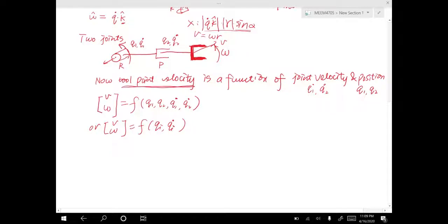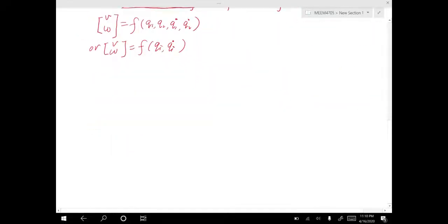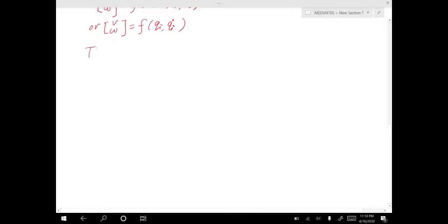If you are controlling a robotic arm and it has multiple motors to control each joint, and you want to finally control the end effector's tooling position and velocity, and now we're talking about velocity, so we want to control the end effector's linear velocity and angular velocity. Of course, we need to know the joint velocity and the joint position of all the joints. Okay, so then let's start a new topic, that is the Jacobian.